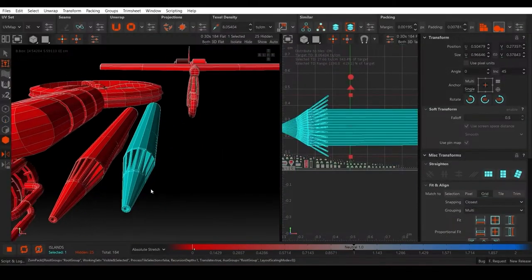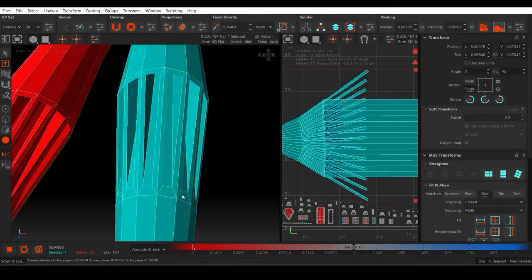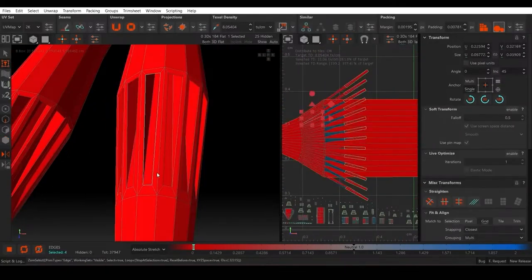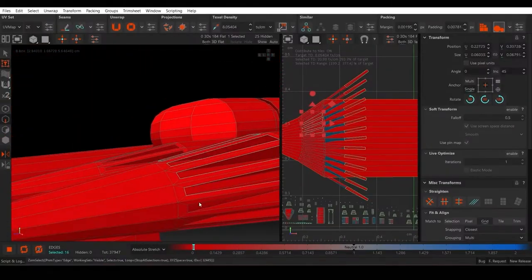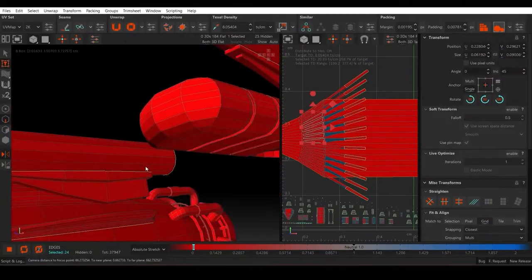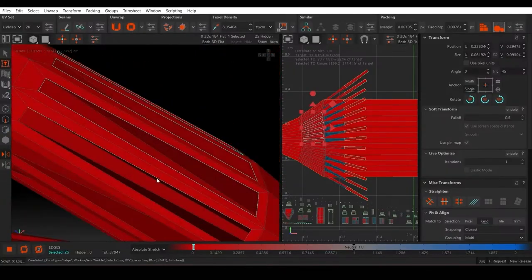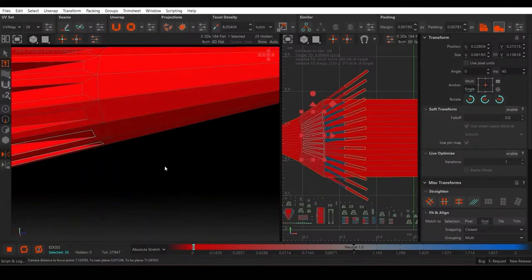You'll notice I'm not creating UVs for these two parts. That's intentional. Later, I'll simply copy another identical piece and replace these inside Blender. Since they're identical geometry, there's no reason to unwrap them twice. This is one of those small optimizations that really adds up on larger projects.